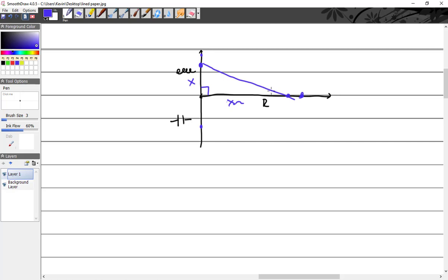Then all I care about is this little angle right here. Because if I had the perfect amount of capacitance to match perfectly my inductance, then those two things would fall right here, if you understand that. So if I had a lot of inductance, whoa, the more inductance I add, the worse it's getting out of phase, right? I need to bring in some capacitors.